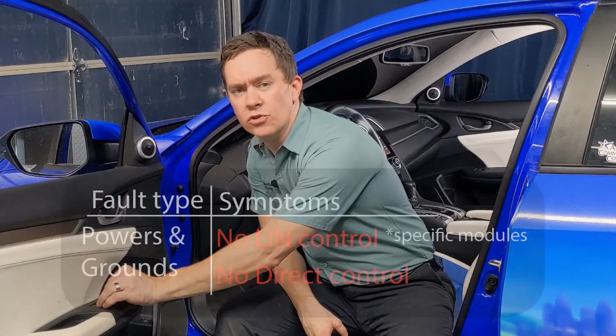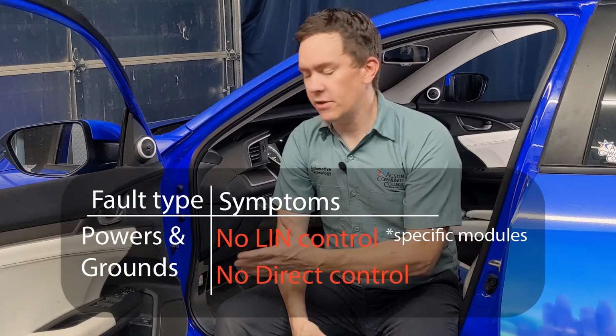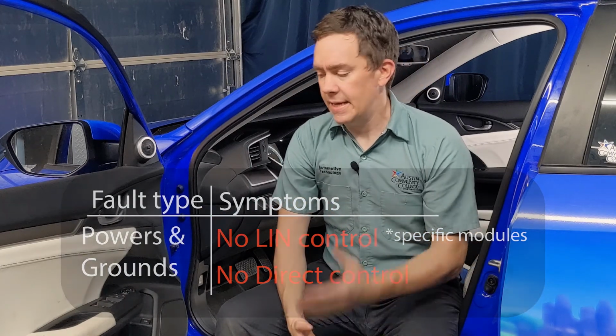It looks like they stop operating, and my components with direct control, like the passenger window switch, still work okay. Everything that uses network communications to operate has stopped at this point. So we see, just like a regular load, a control unit has to have voltage and ground to operate. Open data lines aren't the only cause of communication faults. We saw they can also come from low battery voltage, blown fuses, and faulty grounds.